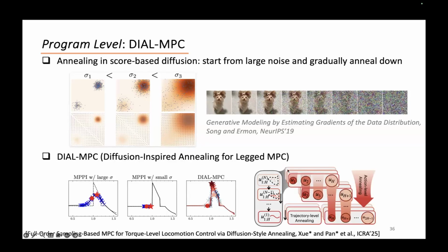And even better, we can integrate this with MPC because MPC is doing receding horizon, right? And then we can control the sigma of different time steps in the receding horizon procedure, right? For the further future, we assign bigger sigma. For the near future, we have a small sigma. In such a way, right, we can do this receding horizon streaming diffusion, right? Because we don't need to do multiple diffusion steps at a single time step, right? Because the whole sequence is doing streaming diffusion, right?